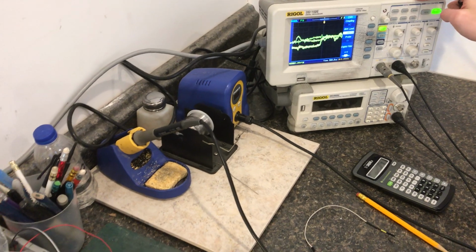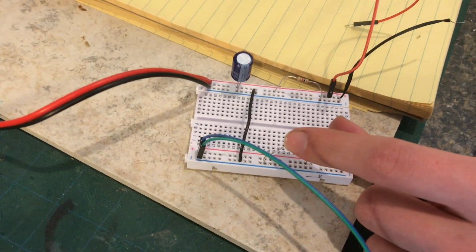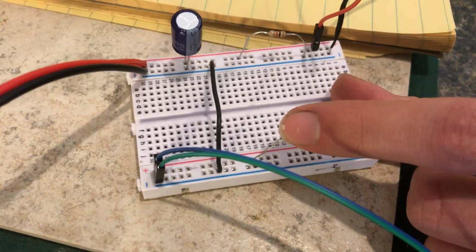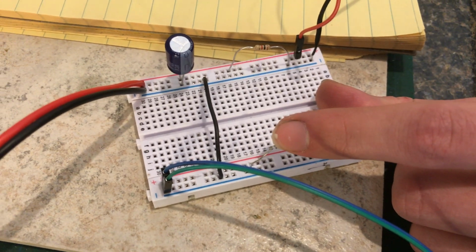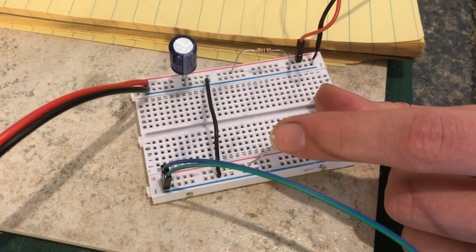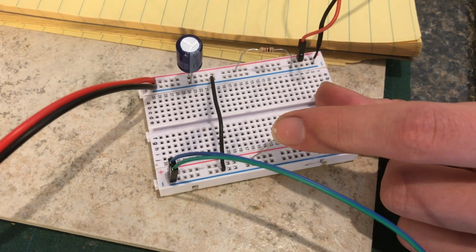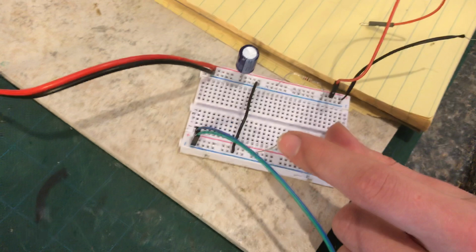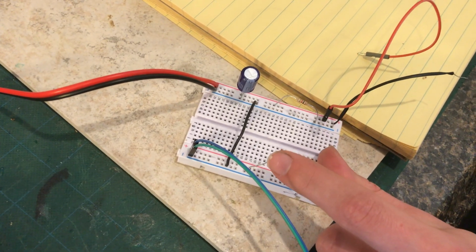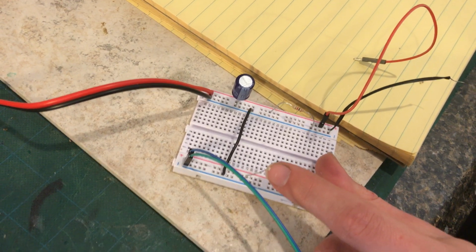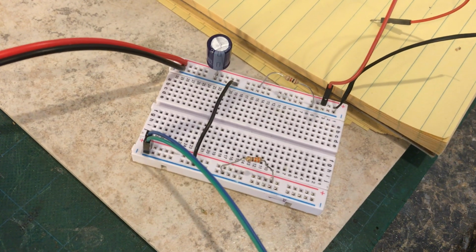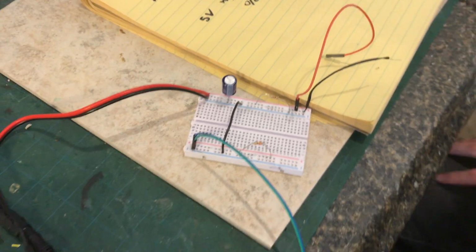Remember, it's important that you test it putting a load resistor in, because without the load resistor, it won't drain capacitors that are in the power supply circuits. It's basically a false reading. You have to measure how the power supply performs while it's doing work. You can't measure how it performs whenever it's not doing work, you know.